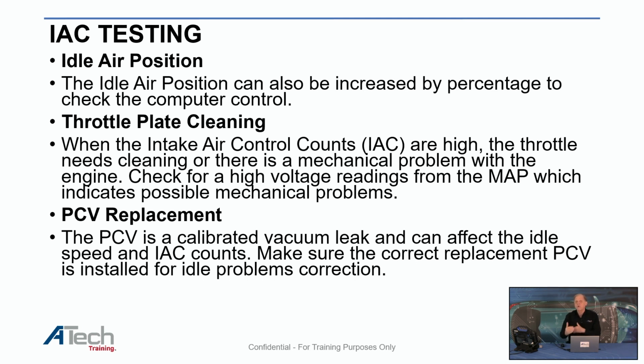So you have to correlate this to a new throttle position sensor and new drive-by-wire systems. It's a little bit different. We need to be able to look at some of the data sometimes because we have to clean the throttle body assembly. I've noticed there's a lot of codes and drivability issues right now where the throttle body assembly itself is carboned up, affecting this.